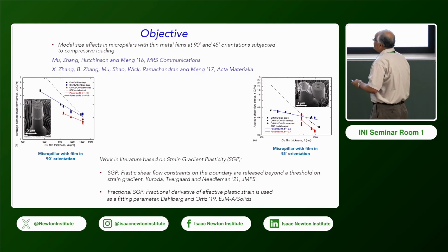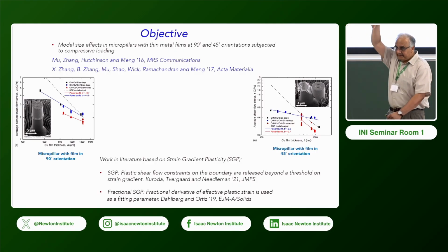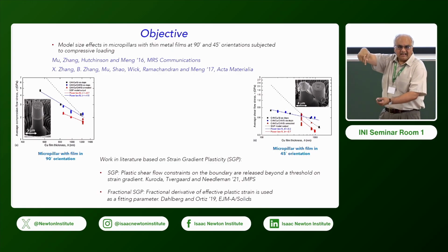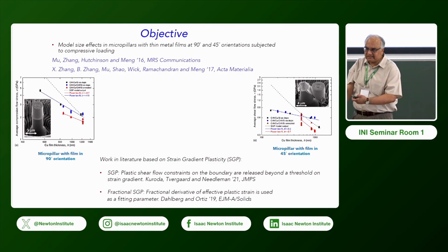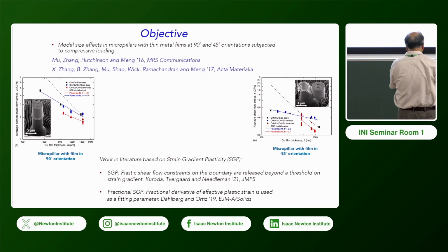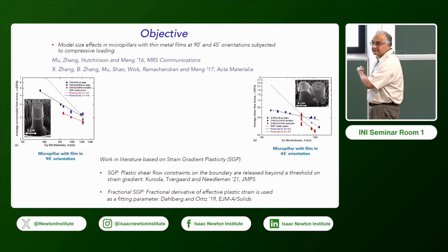You turn this around, and the thin film is now in a 45-degree orientation to begin with, and then you put it in. So if you have some solid intuition, you immediately see that the film will get put in shear. And then what happens is that it breaks. It fractures like this.